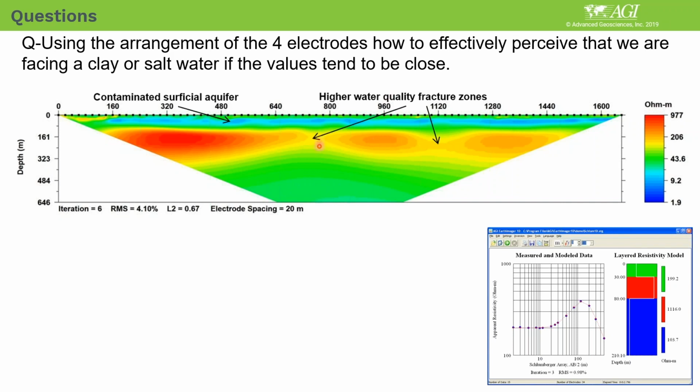Except two areas, like this fracturized zone. When you drill here, you really get to where the aquifer is. The main aquifer is located underneath this highly resistive layer, which I think is limestone over here. This aquifer will give you fresh water in that case. In order to find this kind of thing, you need to do these 2D studies.